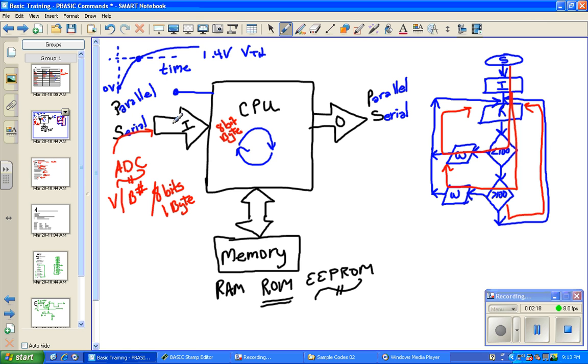Or if you have a component like a humidity sensor which changes capacitance value based on the humidity, you can also use that as a sensor directly into the microcontroller without using the analog to digital converter. This time then becomes your analog variable within your program that you can check to see if it meets one of your conditions.